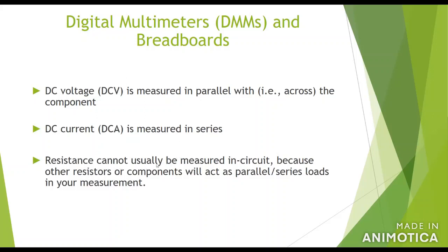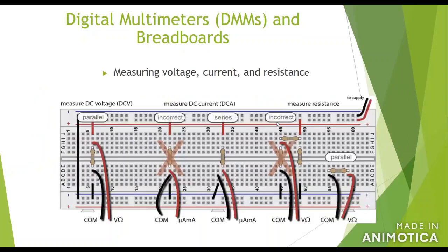For resistance, usually you don't measure the resistance in the circuit, because if you measure the resistance in the circuit, usually you get a wrong display. If you put the resistor into a circuit, it is usually affected by other components connected to it. That's something you have to understand.